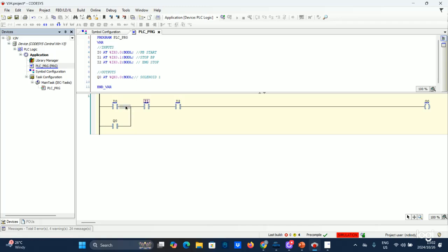So now we'll have to add another. To create an AND condition, so that two conditions are met before the signal advances, we have to create an AND condition here. So AND, it's this and this, another input under the latch of the output. So it's sort of like, if you remember, a series connection. Yeah, in a series connection.